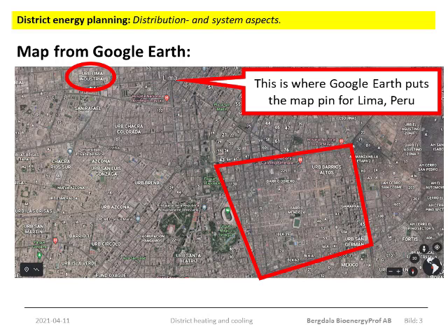Generally speaking, you will first want to collect such data that you can compute the total need of heating based maybe on two factors. First, like the area, the number of square meters, and second, the type of buildings on that land. Single-family houses will need some specific amount of heating. Multi-story apartment houses will have another specific demand. And service buildings like shops or offices will be the main third category.